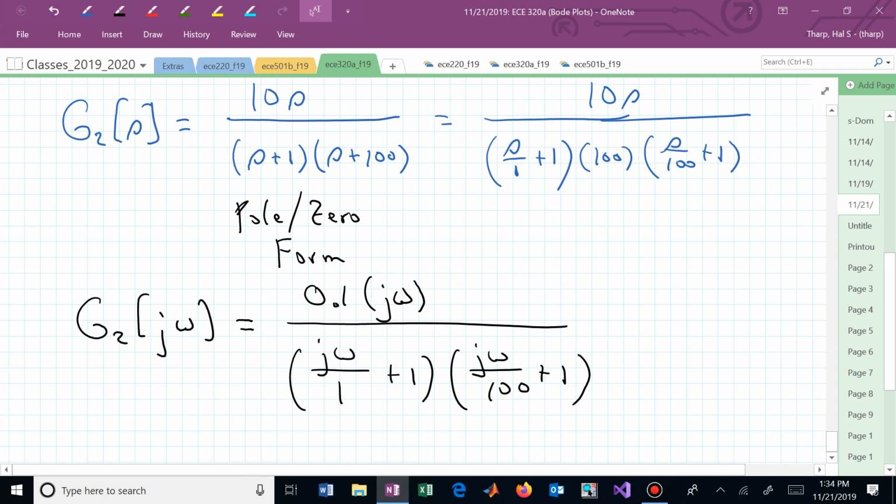What do these pole factors produce at large frequencies? They each contribute individually 20 dB down per decade. We had 20 up from the 0 always. Then at 1, we start going down at 20 dB per decade. Now we're flat, our slope. We're flat until we reach the last pole at 100, its break, and it goes down at 20 dB per decade. What's our slope in magnitude at high frequencies? Minus 20 dB per decade.